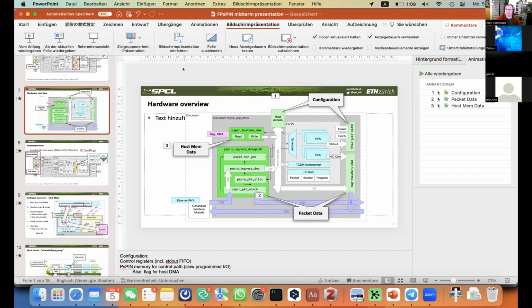But the issue with the slave side device is that you have to handle all of the write byte enables, and I'm like, okay, I'm not sure how I'm going to deal with that. I guess in your case, it's probably relatively constrained to the kind of operations you're doing, so you can simplify things a little bit. But if you're going to make one that works in general, especially for a very wide internal interface.